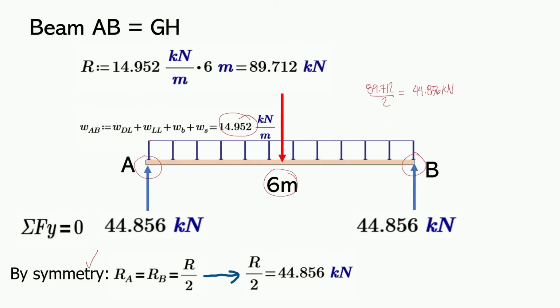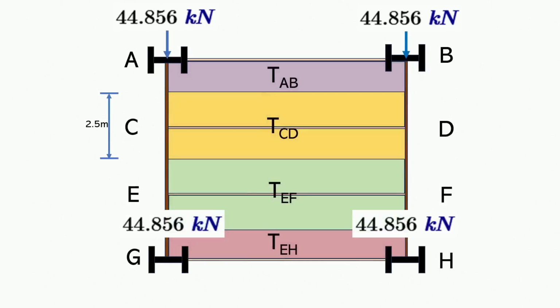Now, if we will transmit that doon sa girders natin, then these reactions will act downward na. Because again, this support is provided by the girder. So kung titingnan natin, ito na yan. Diba, our beam will have a uniformly distributed load, beam AB. And then, it will have its end reactions. Now, yung end reactions are provided by girder BH and girder AG. Kasi diba, itong beam, nakapatong yan dito. And so that's why yung beam reactions natin will be transmitted dito sa girders natin.